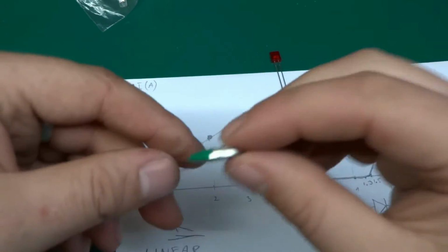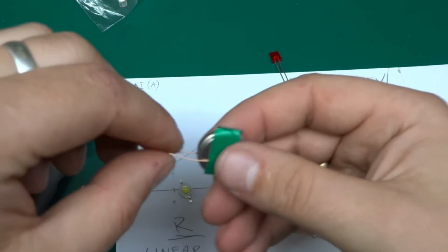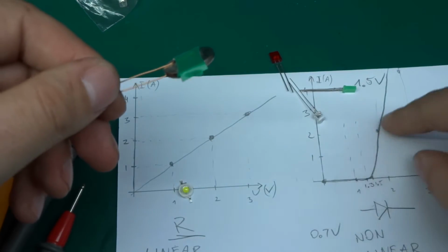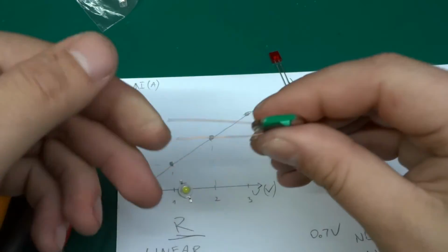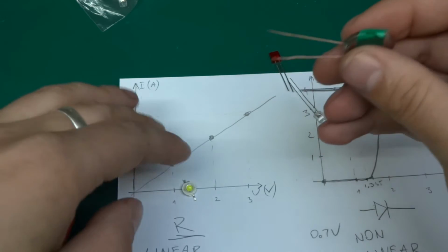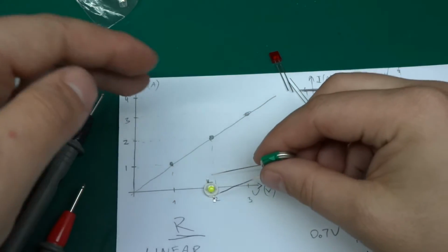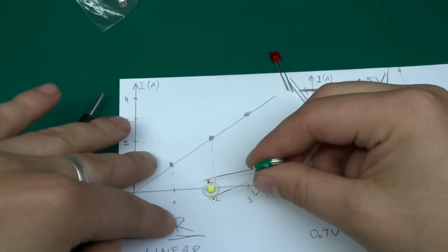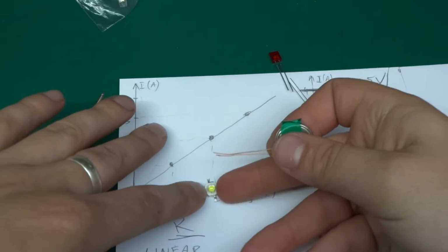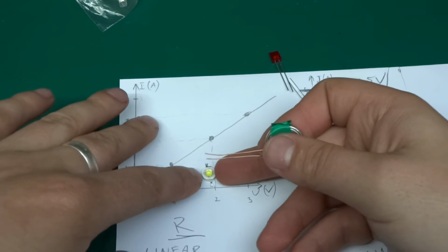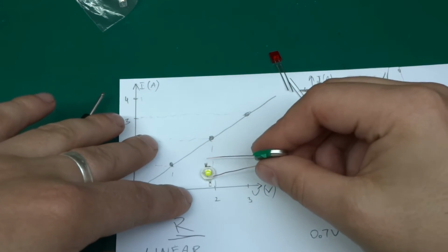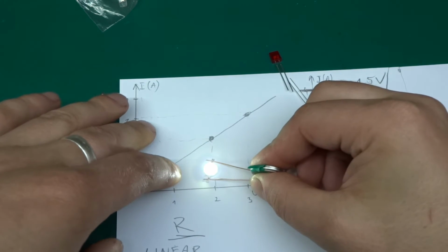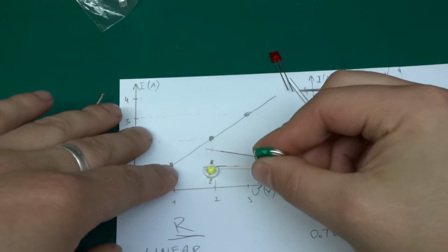And the beauty of using this is those batteries have got quite a bit of internal resistance, which dampens down this effect, and it will not kill your LED. It's 3 volts with quite high resistance. It will be safe. In this way, it will only put out a few milliamps or so, so it will not damage it. If you've got a short leaded LED like this 1 watt LED, or your LED is soldered on, you can put it across, not this way, and there you go, it lights up.